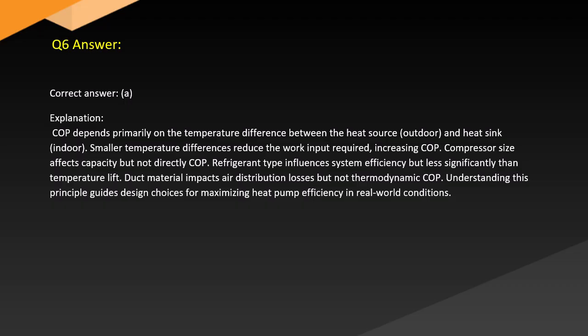Compressor size affects capacity but not directly COP. Refrigerant type influences system efficiency but less significantly than temperature lift. Duct material impacts air distribution losses but not thermodynamic COP. Understanding this principle guides design choices for maximizing heat pump efficiency in real-world conditions.